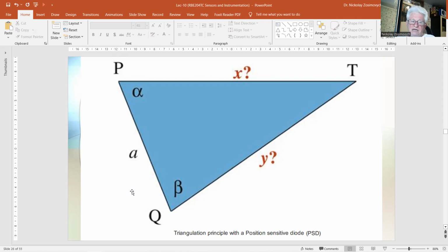Note that the relation is only valid for a limited range of distance L to the object. When the object is too close to the sensor, the distance X of the reflected spot will be beyond the range of the sensor. And this relation allows a straightforward calculation for the distance of an object based on the measured voltage.